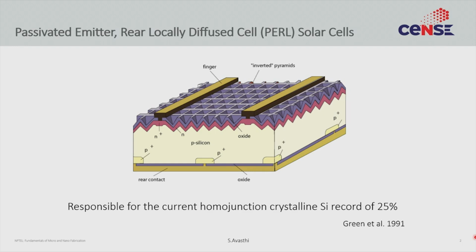So typically one of the contacts is either semi-transparent, or it is completely transparent, or it has a metal grid, something that allows light to enter the cell and be absorbed in silicon. So that's point number one. The other thing is that an efficient solar cell tries to reduce recombination losses.